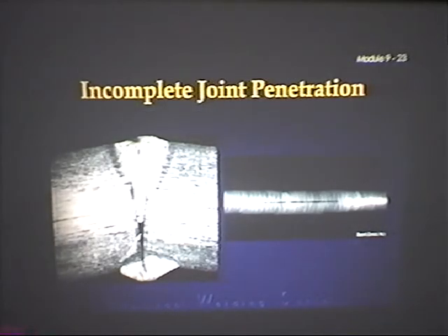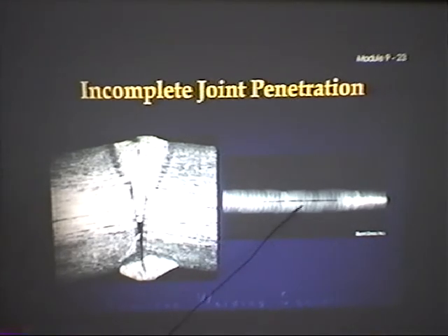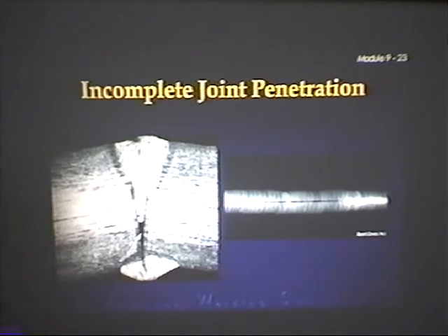Here's that same photograph again, and also now they've thrown up an X-ray. You can see it's really distinctive, really easy to see on an X-ray if you have incomplete penetration.